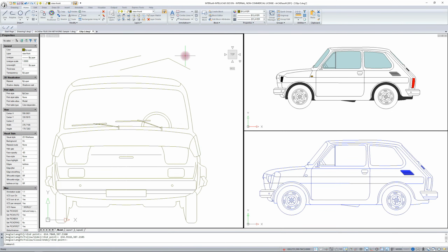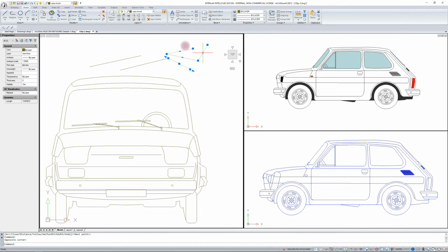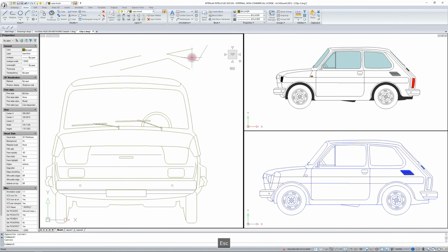OK. And under P, there's a polyline. I can choose, and it's definitely a polyline. You can see from the selection that we have line, and here we have polyline. This way you can customize keyboard shortcuts and aliases and all these elements that are precisely in the program.